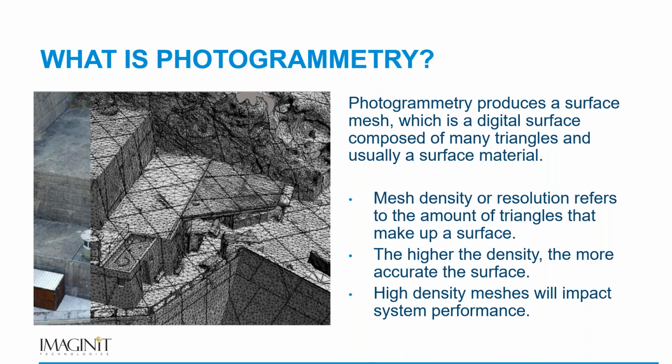One thing that's really important to understand is the mesh density, or the resolution of the mesh, and I'll show that in my demonstration part. With photogrammetry, we have the ability to make a very dense mesh from the photos that we're taking and put that into programs like 3ds Max, or a couple of others that I will mention on the next slide. Ultimately, the density is important because we need to know how it impacts performance on our computer, but also if we're going to share this file out, we don't want to bloat the file size if it's unnecessary.